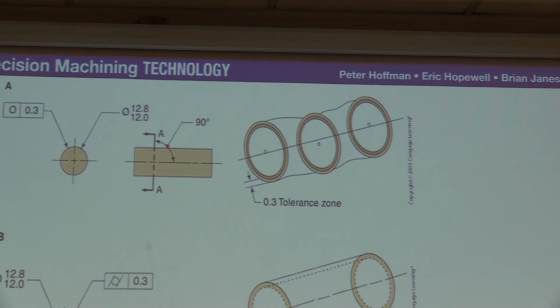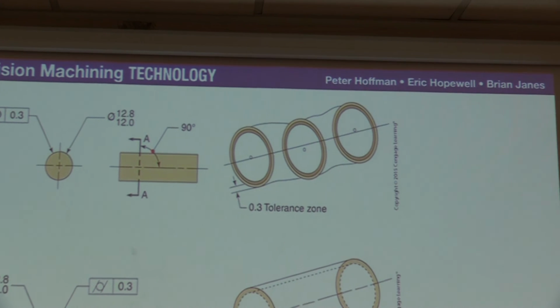You can use a datum line that can be an imaginary point anywhere here. A lot of times in cylindrical parts, your center point is always going to be one datum line. Okay? You're going to pull a lot of measurements off of your center line. You're always going to stay at the center line of a bed or fitting, a round portion, and so forth. Okay? Then you can work your way out from there.